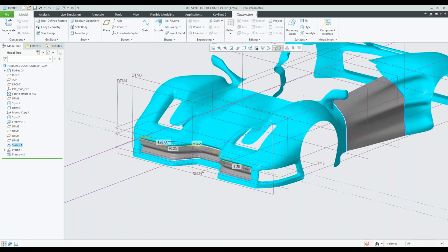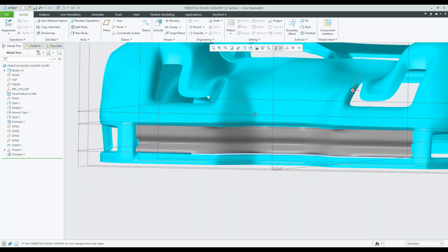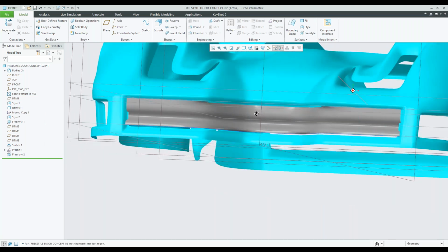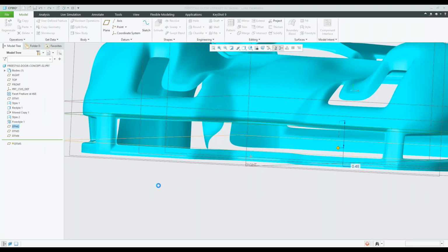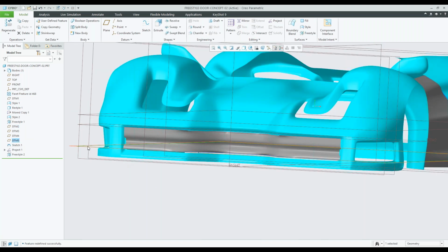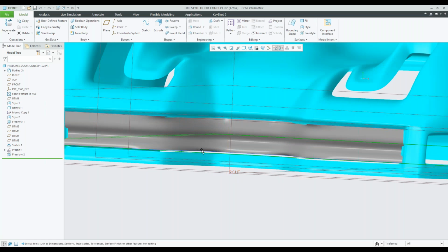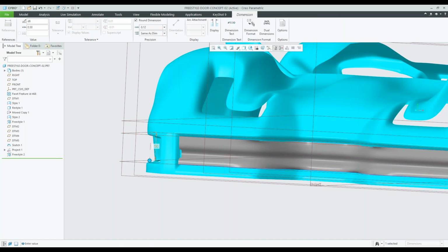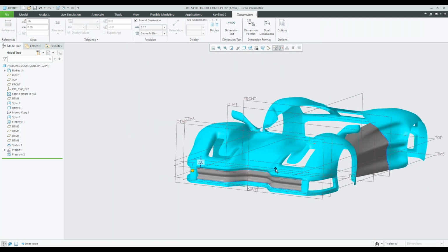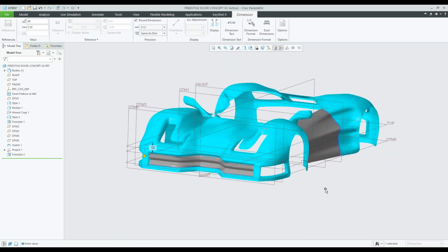All right. So there still has to be some work done too, right? I might have to adjust those planes as well. So I might want to grab this plane, edit that dimension. Let's go to Edit. We have a little bit of a gap here, right? And let's change that from 0.48 to 0.5. And click Enter, and now we don't see that gap there, right? So a lot of people think, again, that with ISDX and Freestyle you really can't control that stuff, but you actually can to a degree.